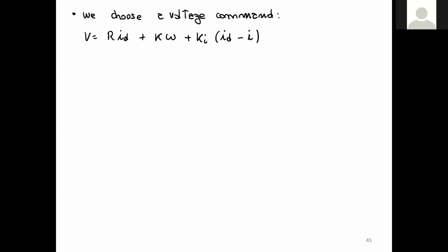The position controller spits out a desired current to be tracked, and an inner loop, think about a smaller, faster controller inside, that is the current controller, will try to track this desired current applying a voltage. So the voltage is the output of the second controller, the inner loop current controller.